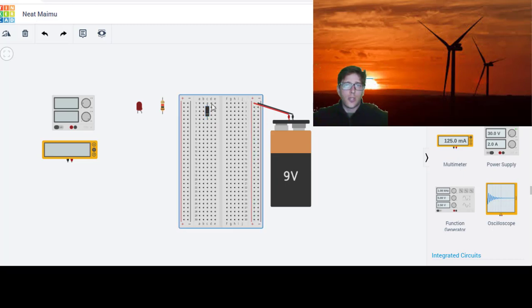So we're going to put in the power to this. We're going to go right here from the red rail into power, like that is red. And then our black rail, we're going to go down here, and we could put it directly in. But remember, we always want a resistor in everything that we do. So I'm going to put the resistor right there, and then put this in here. If it didn't have the resistor, it would have a really high current. That wouldn't be a good thing. We would not want to burn out our diode. And so we can just do this.